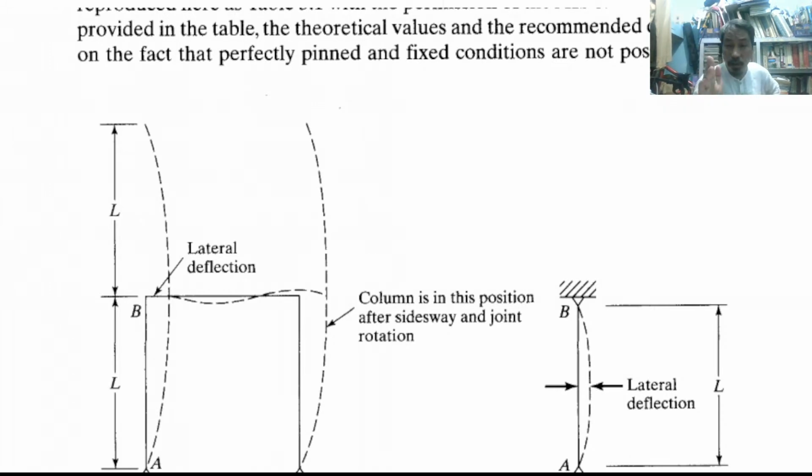After locating the inflection points, find the distance from one inflection point to the other. Then use that as the value of K. That is the K factor. If your unit is already in linear meter or linear foot, that distance is actually the effective length. If your unit is dimensionless, that is the K factor.